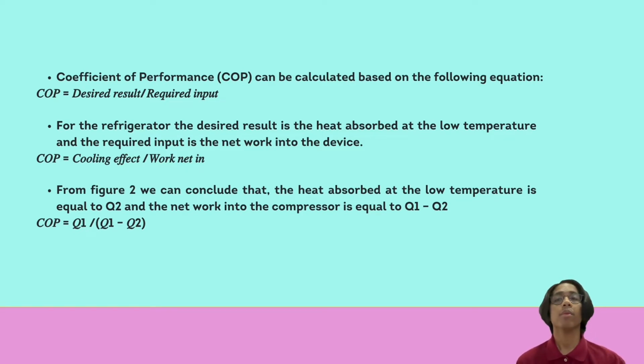And lastly, from figure 2, we can conclude that the heat absorbed at the low temperature is equal to Q2 and the net work into the compressor is equal to Q1 minus Q2. Hence, our COP is equal to Q1 divided by (Q1 minus Q2).